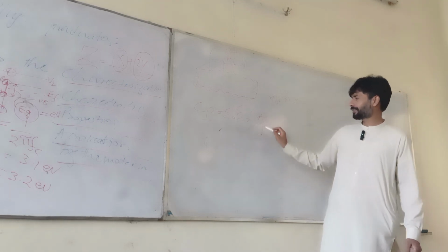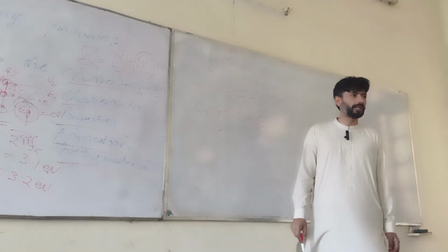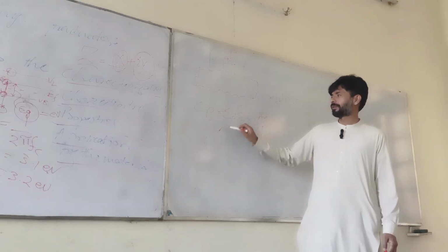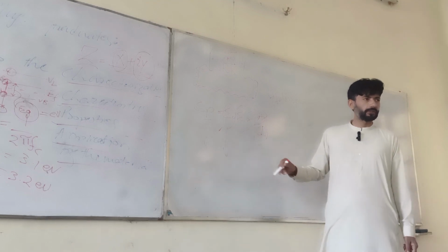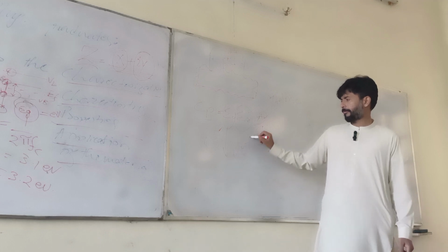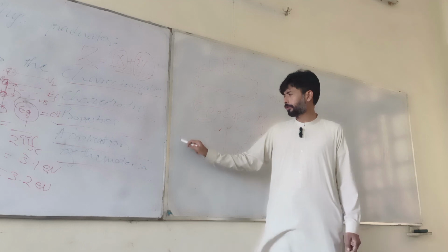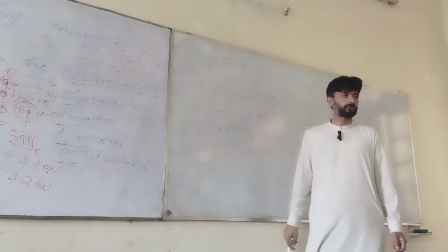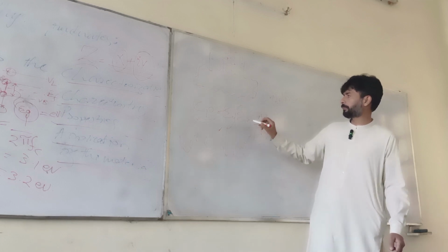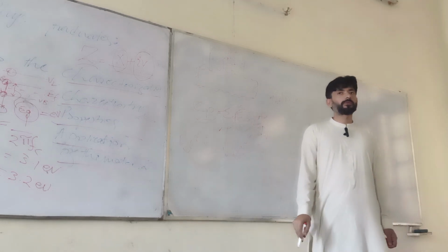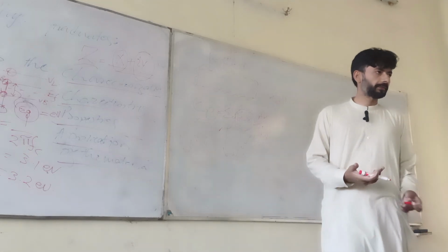Here is the thickness. The area can be derived from the diameter. This is the permittivity of free space, farad per meter. And this can be derived through the LCR meter, from the instrument. So, knowing all these parameters, you can derive the relative permittivity of your material, also called dielectric constant.